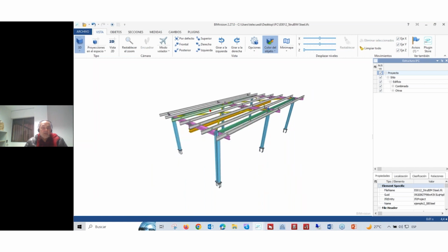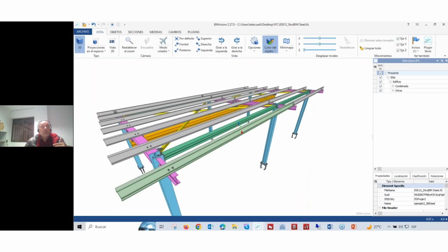That means that, for example, all the braces on top, you are going to classify all the profiles according to the fabricator. The industry might tell you that you can only have this profile, and you can have it several times in the structure. Just make sure that you do it once, and you start selecting the dimensions, the drills, the welding part in the factory, and then you can process this.